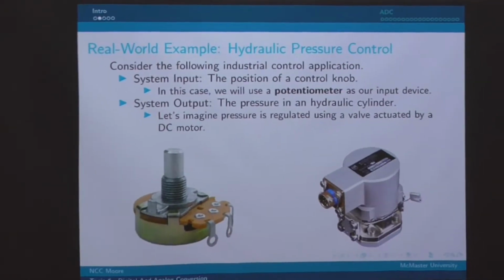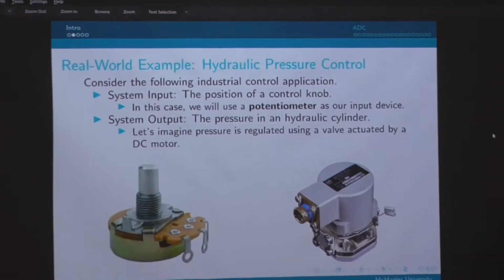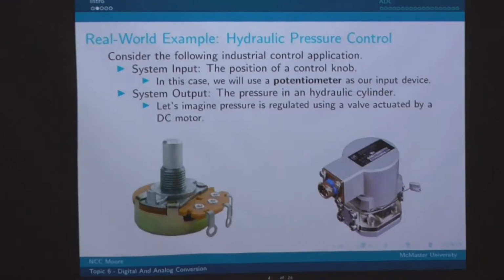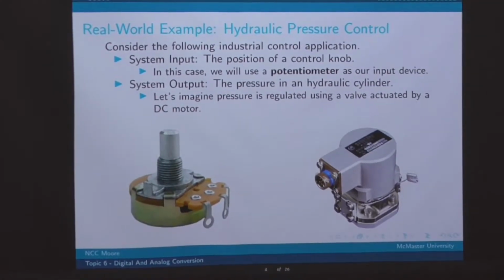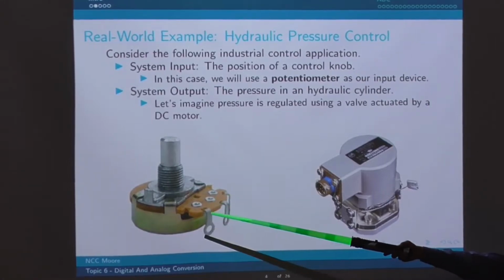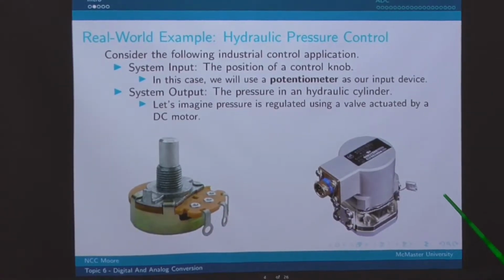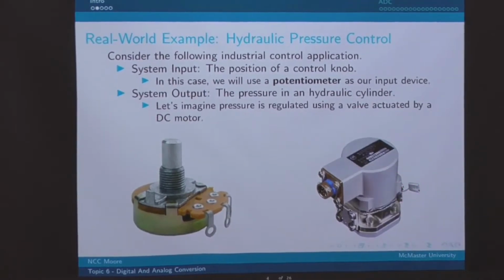The voltage level needs to be controllable, right? So that is an analog output. If we want to wire that to a controller, we're going to have to take this guy, convert that to a digital signal, do our processing on it, and convert it back to an analog signal to run the motor with.